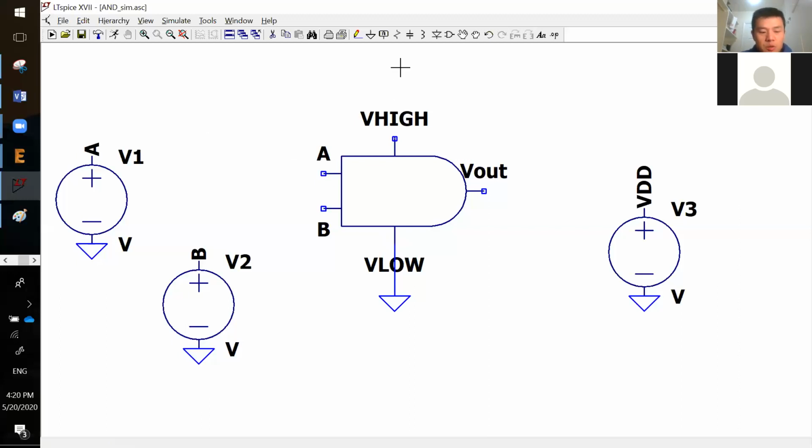So what you need to do is wire this out first in this upper layer. We can say it's a higher hierarchy compared to the symbol itself. This simulation layer is actually higher on top of this symbol. So you need to rename the pins, rename the label to whatever you want to use, right? Keep in mind, don't forget to connect the wire to it. And copy.